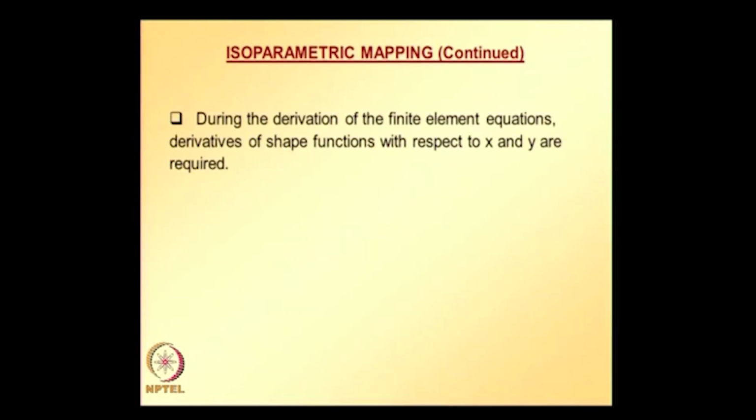And also, during the derivation of finite element equations, derivatives of shape functions with respect to x and y are required. Since shape functions are defined in terms of parent element coordinates, we can easily find the derivative of the shape function with respect to s and t, and once we get shape function derivatives with respect to s and t, we can find shape function derivatives with respect to x and y using chain rule.